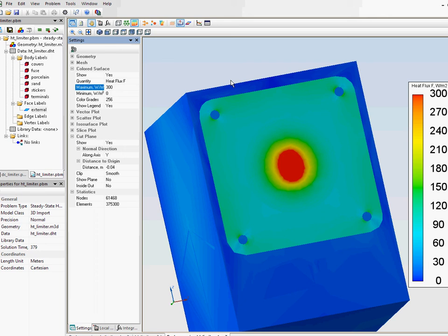You can see there is a heat flux inside, and once the heat flux reaches the boundary condition, the flux is removed. There is no heat flux in the outer sand. The path of the flux is the following: fuse, sand filling, porcelain body, boundary condition. So our assumption about the sand and the boundary condition was correct.